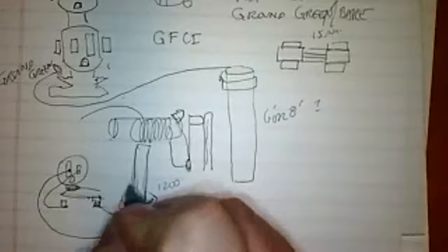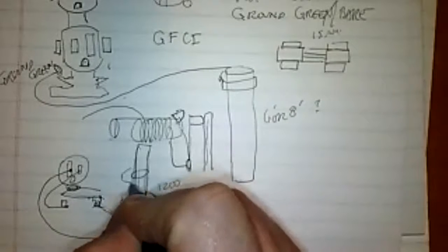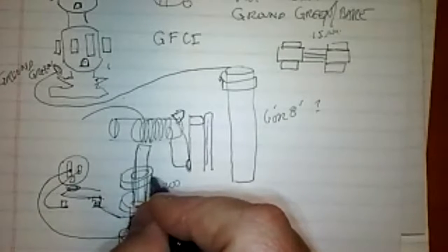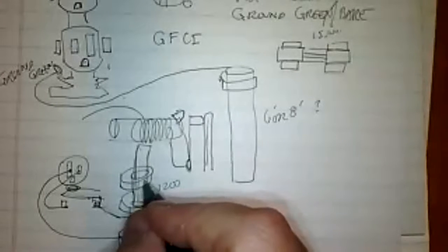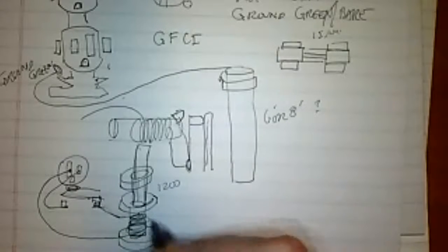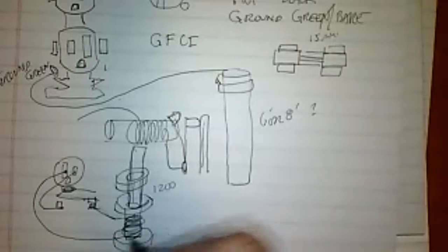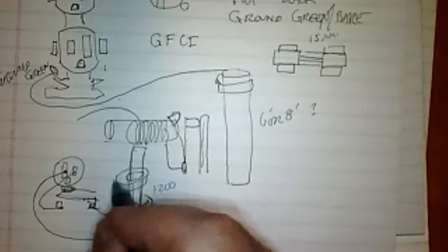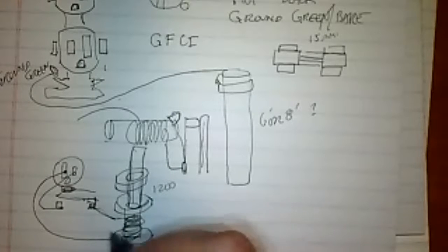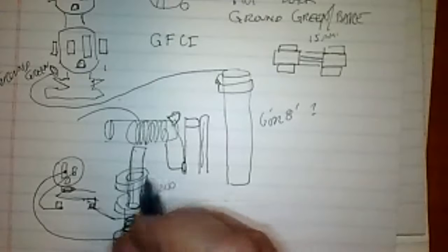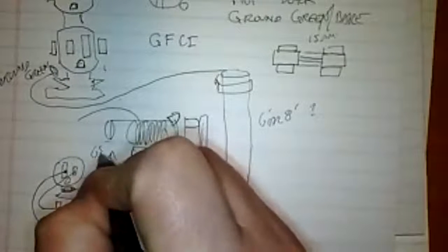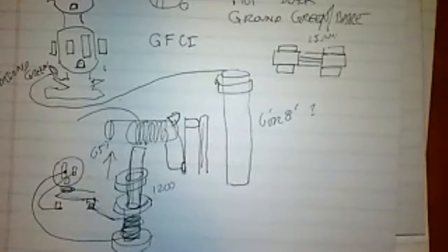So when I did that, then you can take a cylindrical disc made out of aluminum on it. And I would take that aluminum disc and dip it in liquid nitrogen so that its resistance would become really, really low. What happens when I connect this circuit, current runs through here that's AC, and the instant the AC is going around this way, it's inducing a current going around the opposite way in this, and they repel each other. And then it switches to going around this way, and then this one switches and goes around this way, and again repels this. And by doing so, I was able to shoot this thing up about 65 feet. That's basically an electric rail gun, if you will.